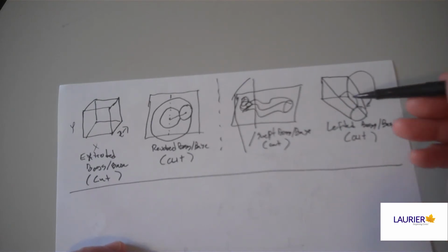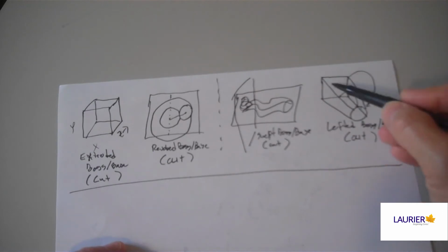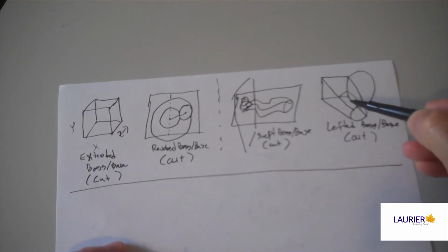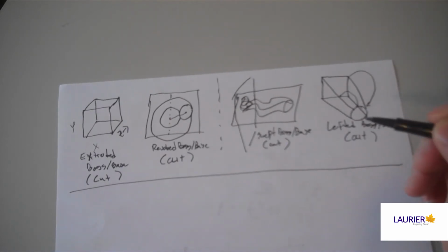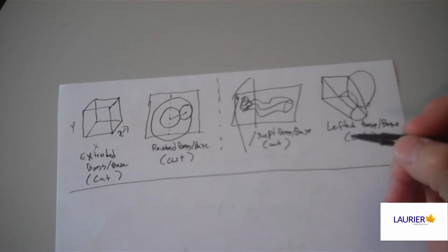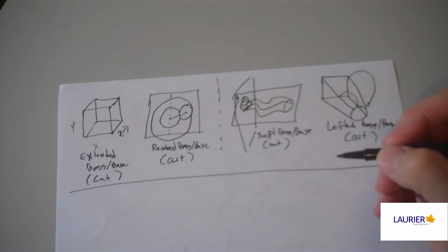Unfortunately, there are some problems that can crop up and cause errors, so we're going to cover them now so that you don't get confused if they come up while you're doing a drawing later on. If we look at them now, we can try to avoid them, or at least find them and fix them. If you were listening carefully to what I was saying earlier on, you would have heard me very specifically choosing the words closed contour time and again.